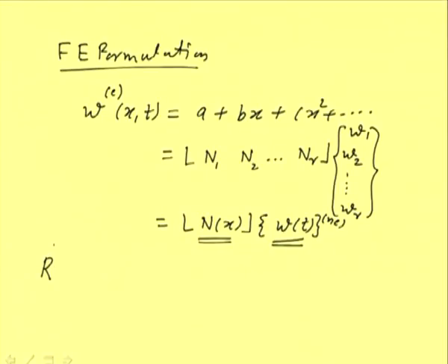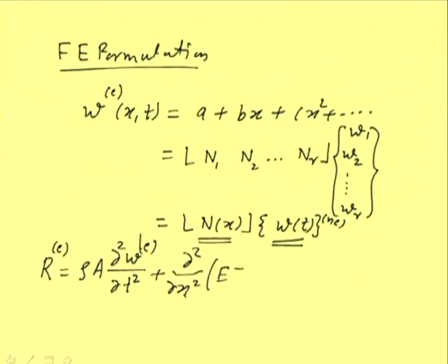So, once we substitute this approximate solution into the equation of motion, the residual will be this, rho A, this is the inertia term. Now, in all displacement terms we are writing for the element. This is the inertia, this is the elastic term, then forces.